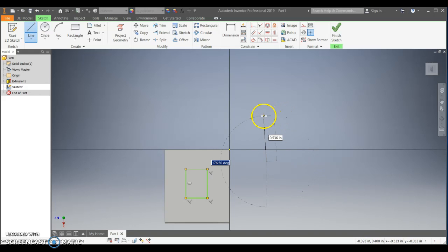So this is where geometry really becomes real for you, and we get to apply some geometry in a really cool way. If we're creating square-like objects, well then we know that each corner should be a 90-degree angle, and so we would make them 90 degrees from each other. And as you can see, Autodesk Inventor is intelligent enough to kind of follow your pattern, and it will do this stamping with the click options when it feels like it's aligning. So if you can see that there, it feels like it's aligning with that line, so it kind of creates a little stamp. You can see it kind of jumps to that line. And again, Autodesk Inventor is just trying to follow the pattern of the work that you're doing.